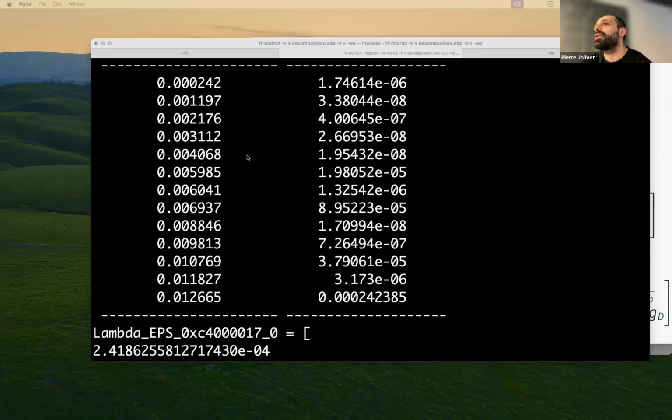Neumann is a natural boundary condition, so there is nothing to do in the linear system. If you have a pure Neumann problem, the value of TGV does not matter. Whether you put 2, -2, -1, it does not matter.